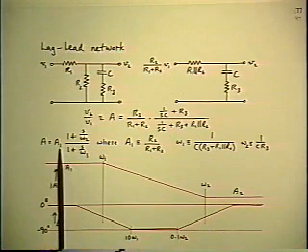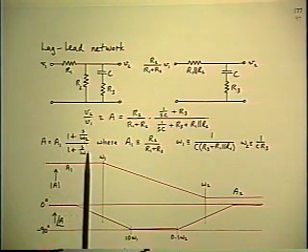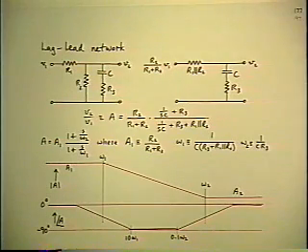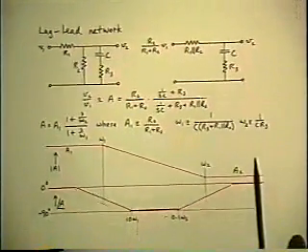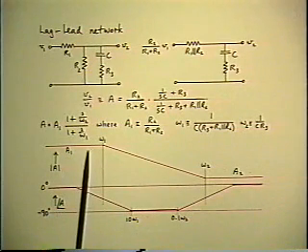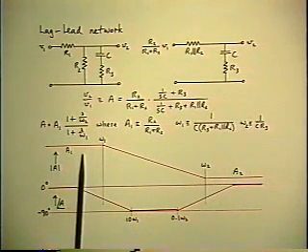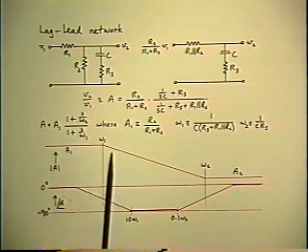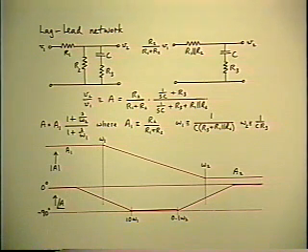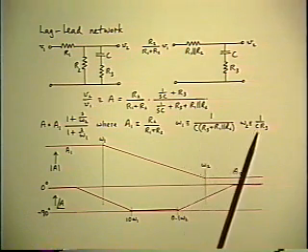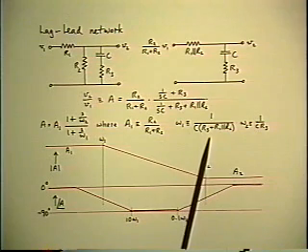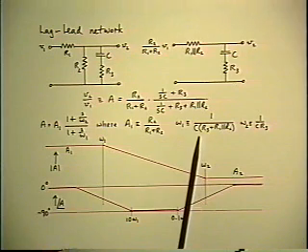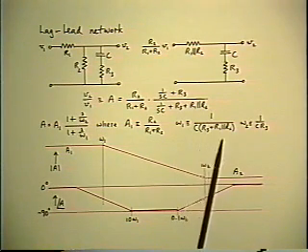And then, starting with the A1 as reference gain, at higher frequencies the pole and the zero will modify that result. So the next thing we want to look at is the sketch for magnitude and phase versus frequency that this network has. So starting from A1, the reference gain at zero frequency, as we go up in frequency we'll encounter either the pole or the zero, depending on whichever comes first. When you look at the expressions for the pole and the zero, you can immediately tell that the pole will come in first.